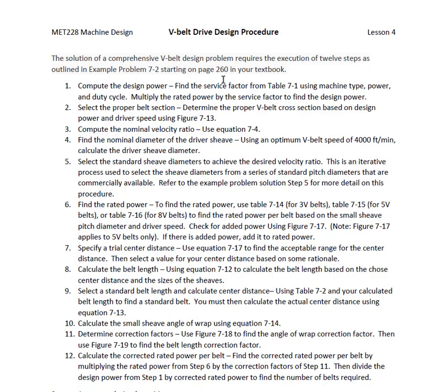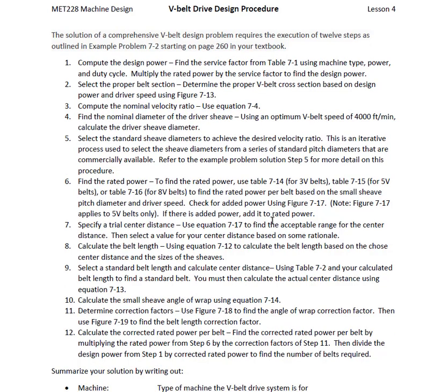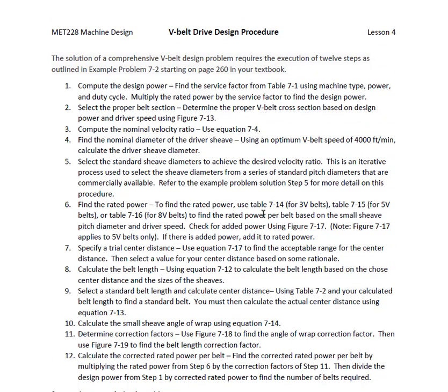You're given some things in your problem. It'll probably tell you it's a V-belt drive design, and it'll tell you what the power is and what the speed and power rating of the power source is, whether it's an electric motor or something like that. Then you have to go through these steps of designing the drive. The purpose of this file is to summarize how to do it, and also to provide you all the tables that you need to solve one of these.